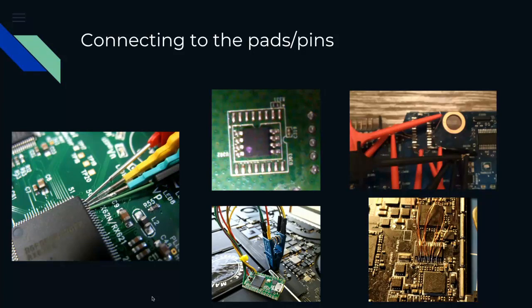Some are very expensive, like $100 per probe, but they can pick up very thin pins, in that case the pitch. For SOIC package devices, you also have these test clips that you can plug onto the top of the chip to expose the pins. Sometimes if you don't have the pin, or if it's very thin, you have to use flying wires and solder on the chip itself.